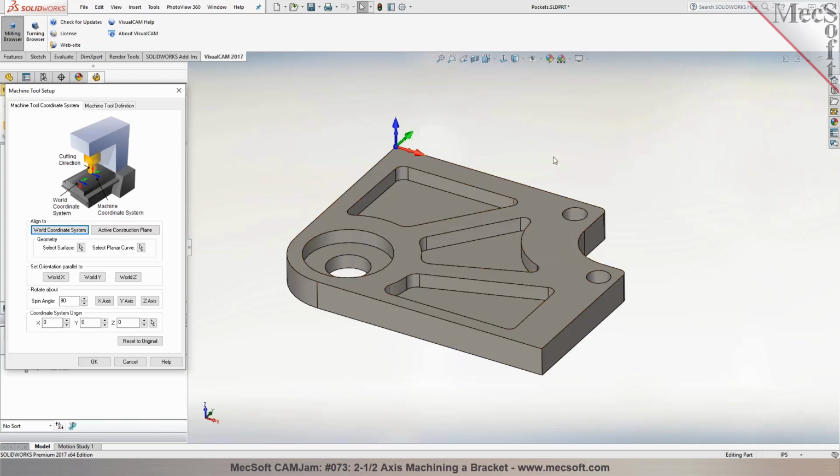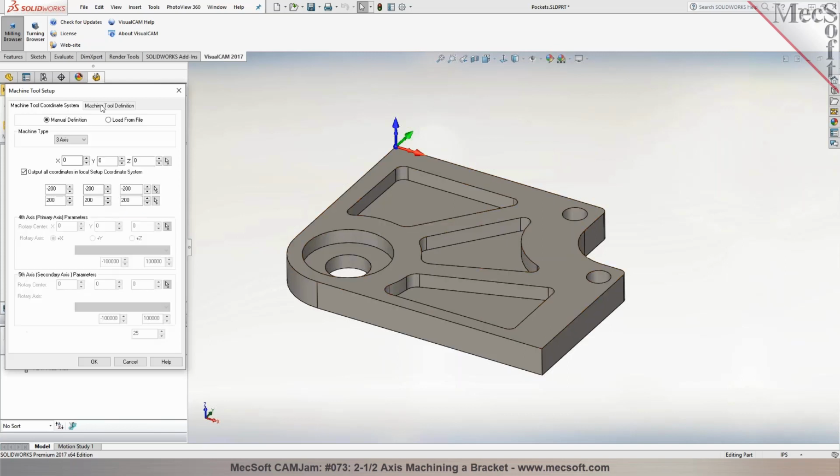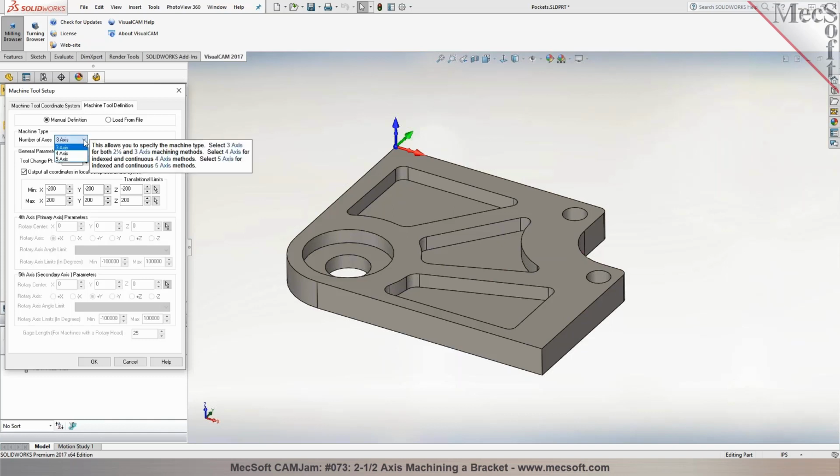Once you establish the orientation, the next step is to define the type of machining process, whether you're going to be doing 2 and 3 axis, 4 axis, or 5 axis programming. We have different configurations of the mill module, starting with standard, expert, professional, and premium. The professional offers advanced 3D milling methods that are more geared towards tool and die making, mold making.